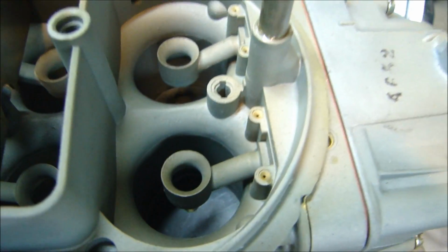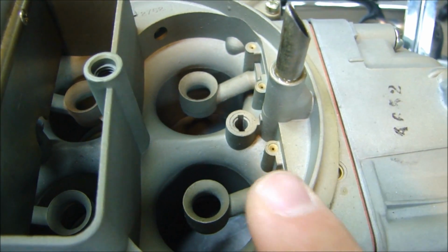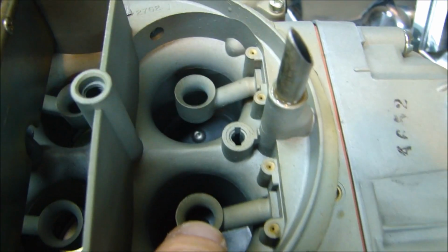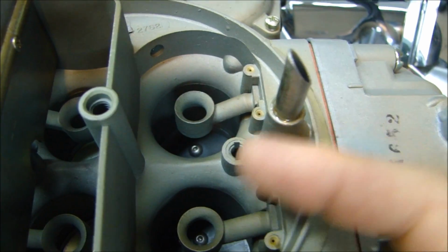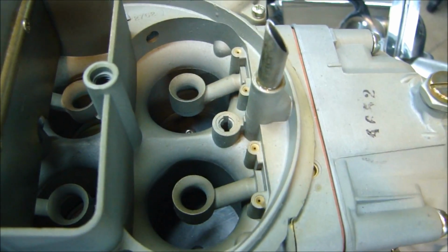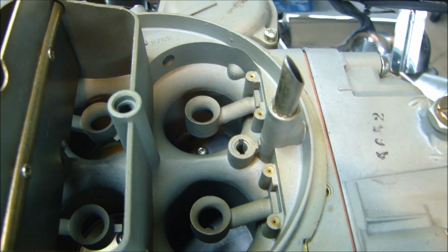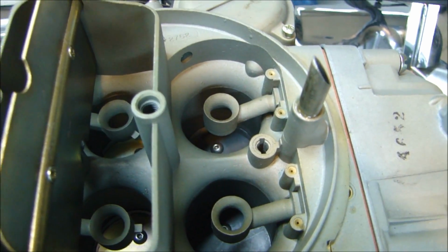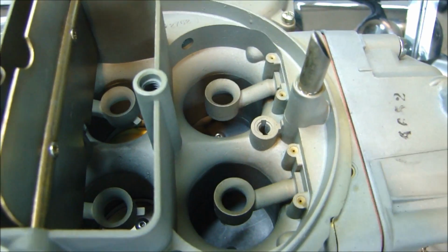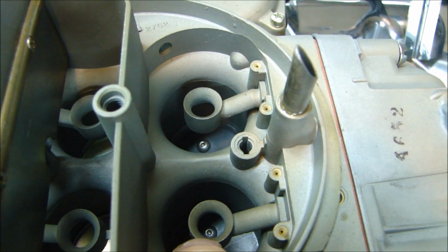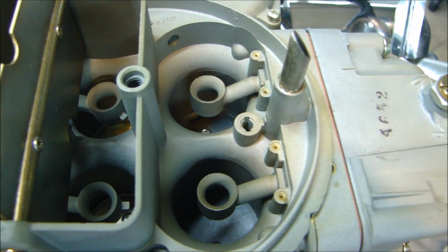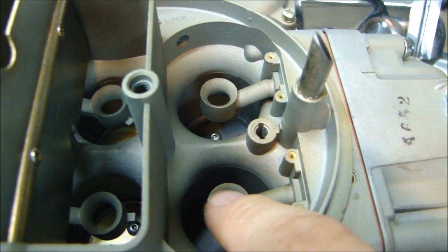So at minimum RPM, you have low vacuum, and if the vacuum drops low enough, the air rushing across your fuel metering ports will not be metering the fuel properly, and that's when you get stall-out conditions and poor acceleration. If you're not metering your fuel, you don't have the right vacuum at idle. Likewise, at wide open throttle, you want only so much vacuum there, because you can be rich or lean based on the vacuum going across your metering rods.